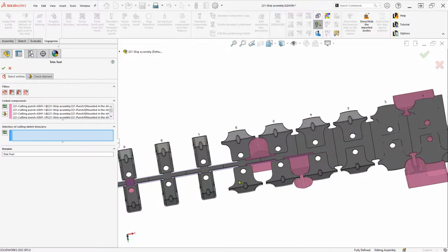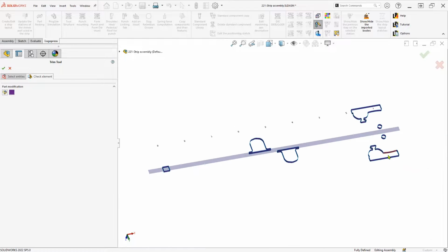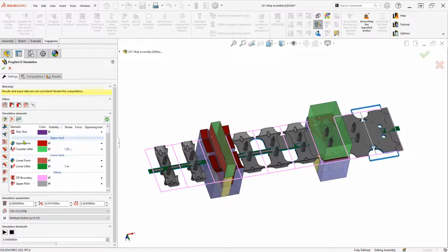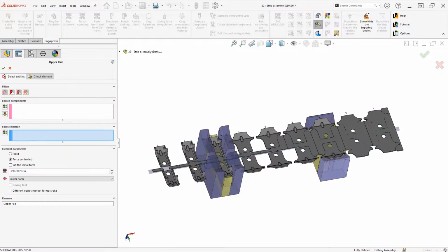The last one here is the trim tooling, because it is starting at the regular coil. It should grab all your cutting punches automatically from the strip layout. So that's for all the basic tooling there. You can start adding more types of tooling from the left column there.